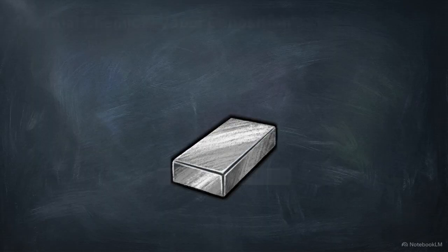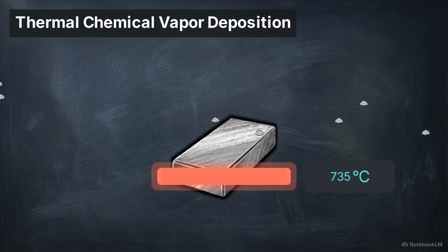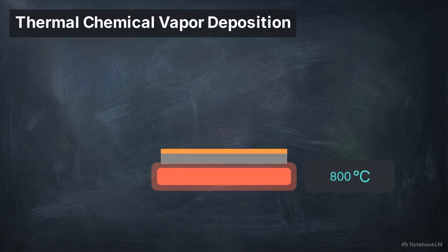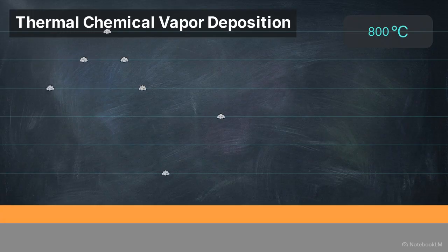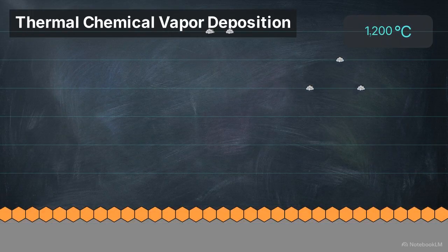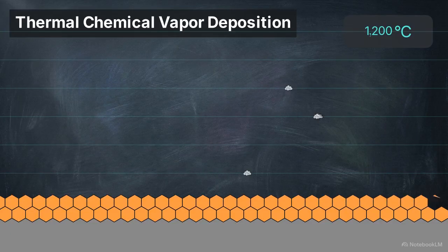CVD. This diagram illustrates the basic thermodynamic mechanism of thermal CVD. Vapor phase chemical precursors are injected into a vacuum chamber. These gases flow over a flat substrate resting on a heated chuck, where extreme heat forces a chemical reaction to deposit a solid layer. By adjusting specific variables, engineers dictate the physical properties of the resulting film, driving up the absolute temperature, and carefully tuning the flow rate of the precursor gases directly determines both the uniformity of the film and its internal crystalline structure.